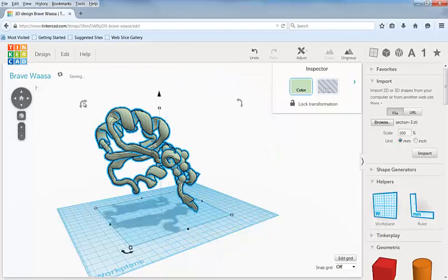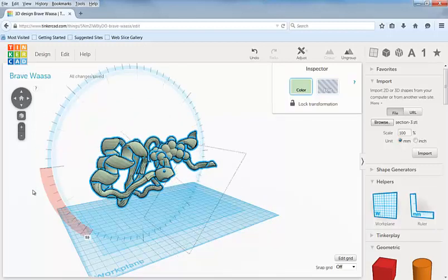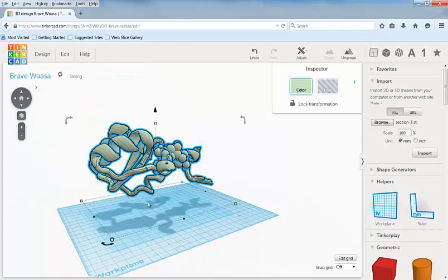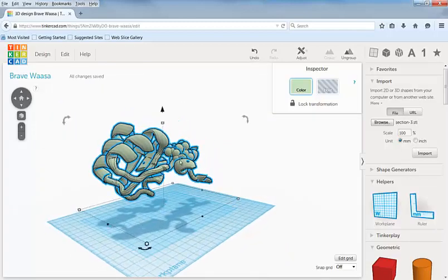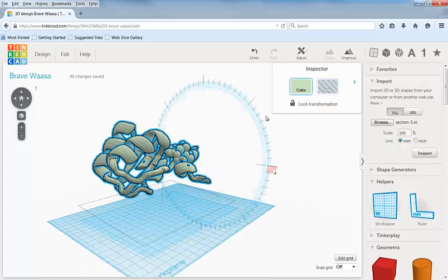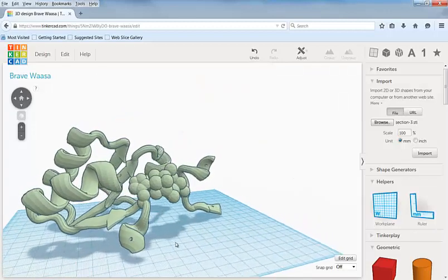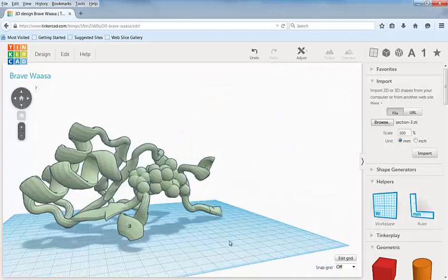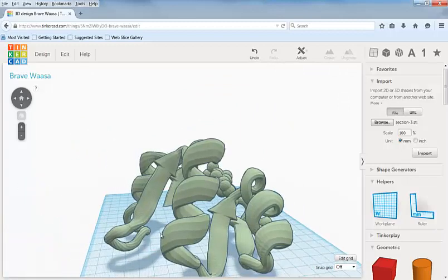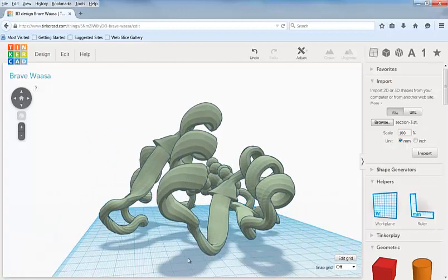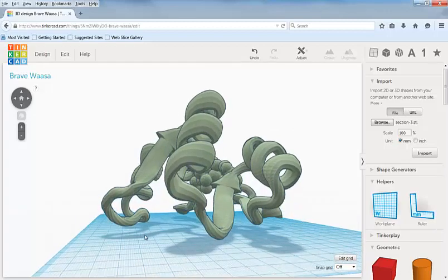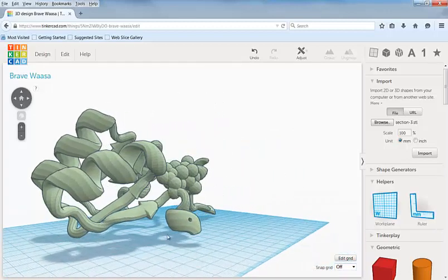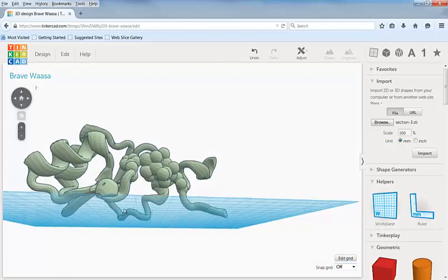So I'm just going to go through and rotate this, to optimize it for printing, so that I'm not printing a whole lot of extra scaffold if I don't need to. That looks to minimize some of the excess plastic that the thing is going to have to print, at least on my 3D printer, to build the scaffolding that goes around this. It gets things somewhat set up.